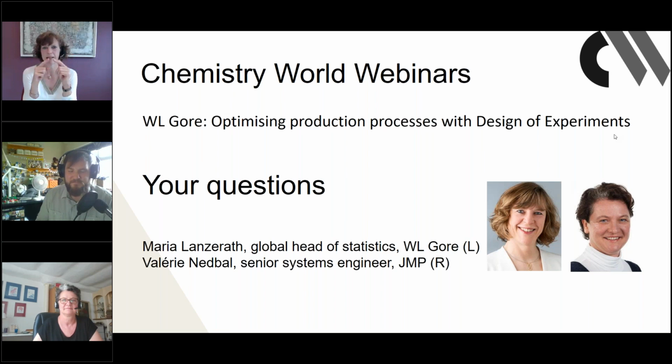So there might be, like what Valérie also showed, a factor correlation. If one factor has the same effect on the results as another one, one of them is good enough. And we knew with those 9 factors, we would have enough chances to find a good process window. So if you've seen, for example, that the effect of increasing temperature and increasing pressure is exactly the same, then you only need to run your experiments with one of those 2.